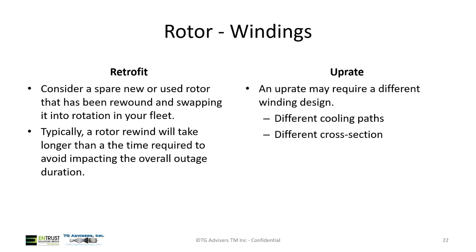So for that differential, you'd have to talk to the service provider to discuss what it is in order to make that decision. But that differential could make it economically viable to justify buying an industry spare, which would be a unit from a different plant that's maybe shut down, or a seed rotor from one of the service providers that's already been rewound. Then they put that in and yours goes back into their program. So those are options to consider.